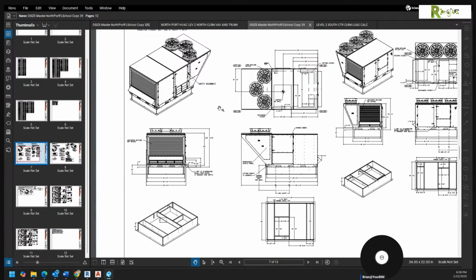And I think that the LOD 450, 500, 600, 900, whatever it is, I don't really think the LOD captures that. And I worry about how the LOD is written because they don't even seem to address the fact that we need to be putting fireproofing on structural steel.